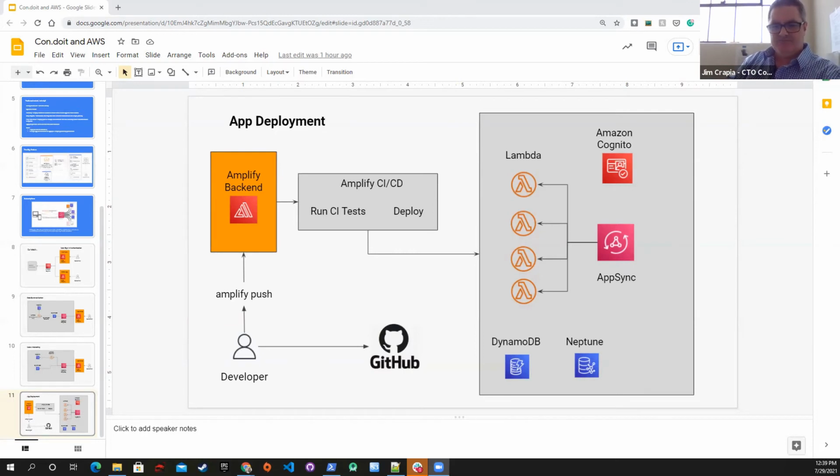The reason is that we can have these devices out in electrical rooms and people can monitor rapid changes in temperature in an electrical system, which could be coming from a loss of power. That could mean anything as simple as a loose lug in a panel that's getting hot, that you're not going to know about unless somebody opens it and takes a picture with an IR camera, and you're losing electricity. It could also mean you're seeing some wire burn or something like that, which could start a fire over time.